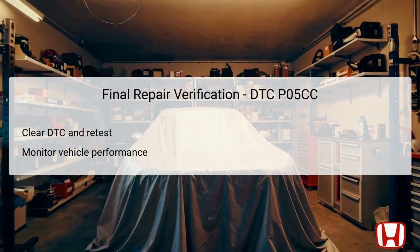Once all necessary repairs and inspections have been completed, it's time for the final verification. Begin by clearing the DTC from the PCM memory using a Honda Diagnostic System HDS tool. After clearing the code, perform a retest by repeating the aforementioned driving procedures to ensure that the VTC system is functioning correctly.